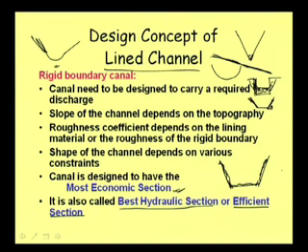But now, what is the difference between best hydraulic section or efficient section? Most economic section is coming because the cost is less. Now, suppose the same area is there, and to minimize the cost we are trying to reduce the length of the perimeter, but in that process we are achieving another objective. The resistance to the flow is coming from the perimeter.